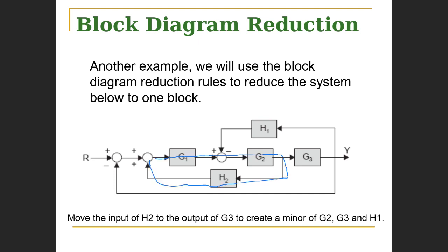Well, it's the same situation. We have a summing node that is in the middle of it, so it can't work. Therefore, we now come to a point. What do we do? Somebody asked earlier, what is the sense or what is the reason for moving pick-off points and summing nodes from input to output? This exactly is the reason.